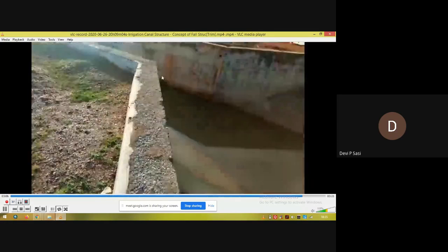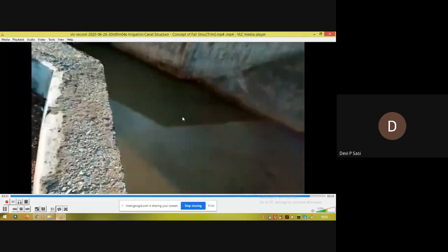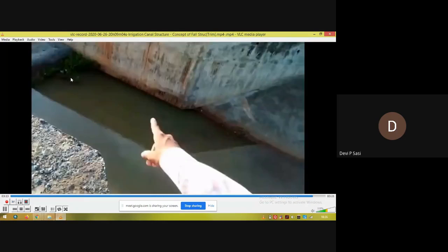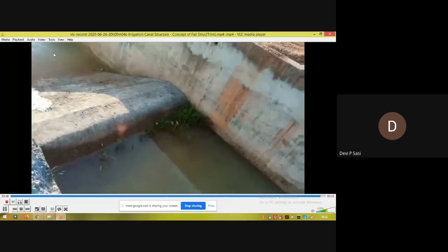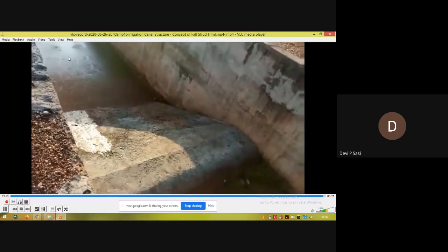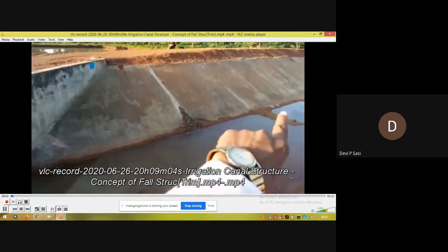So you know the water flows from the upstream region. Here there are upstream wing walls, the upstream approach. Then the water is flowing from the upstream towards the downstream of the crest segment. There is a crest. And from the crest, the falling water moves to a cistern. In the cistern, the surplus energy is liberated or dissipated.